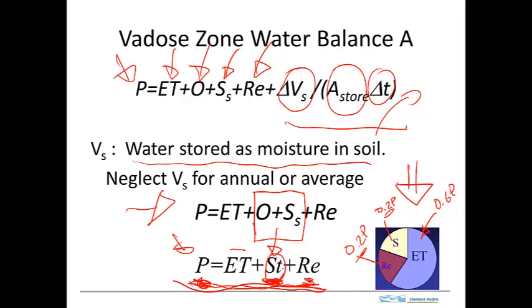Say you had a watershed and the entire watershed was paved, then we would have a very high fraction of storm flow and very little recharge. Okay, so in that case, the pie distribution might look like this. Storm flow might look like that. Might be all of this, and just a small little bit of recharge. Say around the edge of the pavement, or say through the cracks in the pavement.